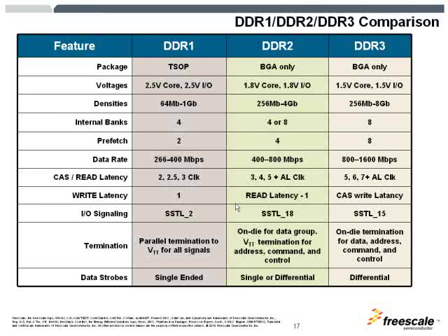However, on DDR3, when you're using a DIMM, because of the flyby topology, the termination for command, control and address are also provided on the DIMM. The data strobes have moved from single-ended to having a choice in DDR2 between single and differential, to differential only in DDR3.